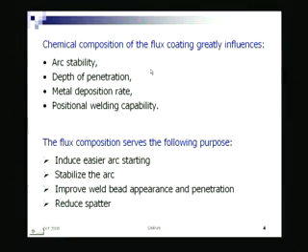If now and then the arc is getting extinguished or deflected, arc power is reducing, increasing, fluctuating, then what happens? Your heat generated is fluctuating, because at the end we are interested in the amount of heat generated. We are not truly interested in what is happening to the arc. Interested in heat generated. Why? Because that heat will determine how much base metal is getting melted. What is the rate of deposition? All those things will depend on the heat, right. That is number one. So, to get that heat uniformly all through, I need a stable arc.